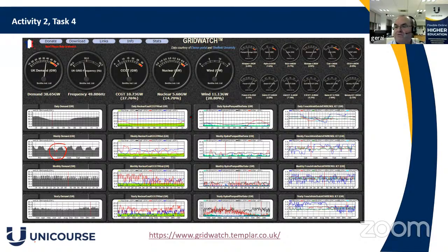So one of them we talked about was pump storage. So you can see there's pump storage up here. And at 5 o'clock, that was actually supplying about, was it 3.3% of the UK energy? But it's only for short term. And what they use the energy storage for is to try and regulate the frequency. So if the demand goes up, they can bring pump storage on quickly, or any of these storage systems that we've talked about. They can be brought online quickly to meet that demand and bring the frequency back onto 50 hertz until the load starts to taper off again.